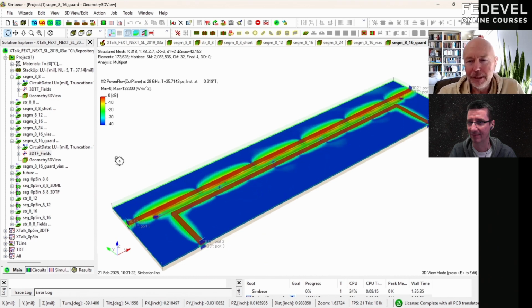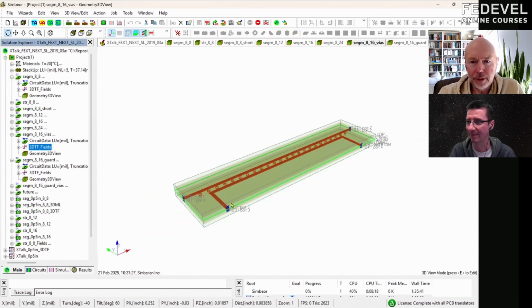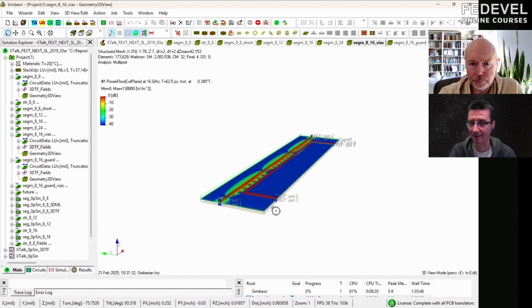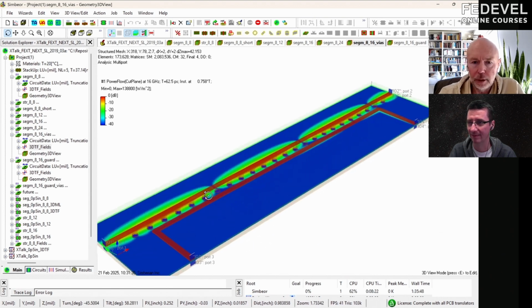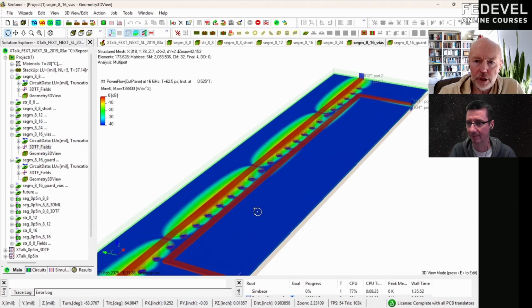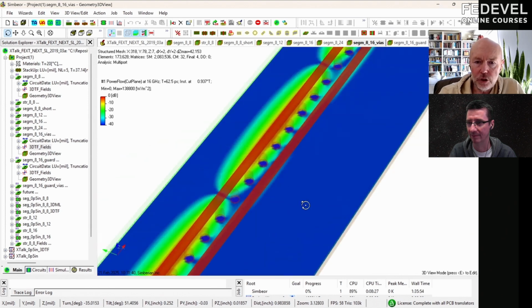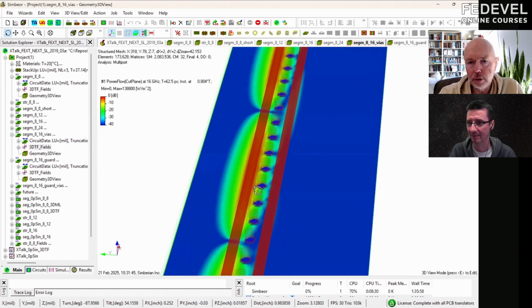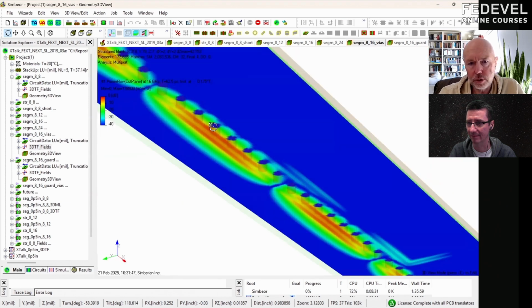So the other extreme is to just put vias in there. So what if we just stitch the reference planes, top and bottom? No track. No track in between, just stitching vias. In this case, you can see that energy gets freely between those stitching vias and gets coupled to this track here.